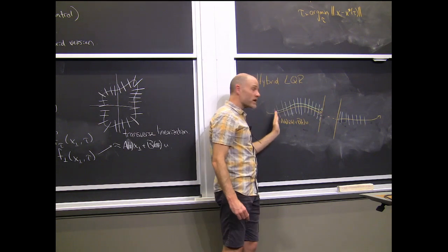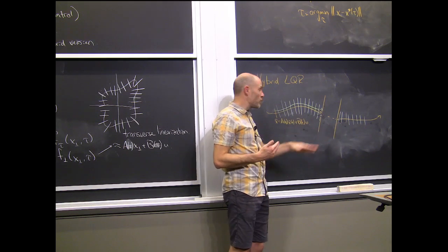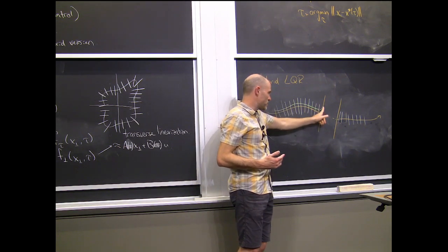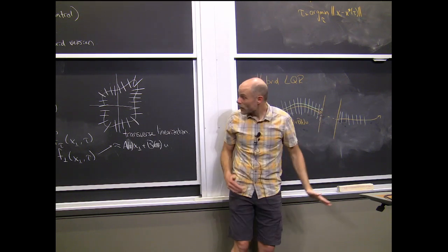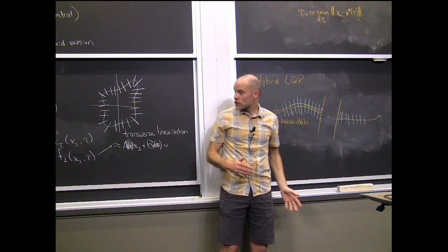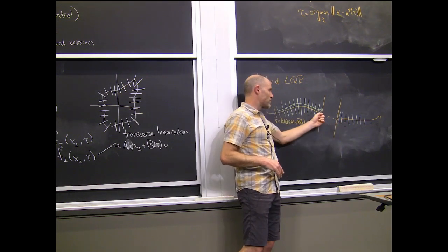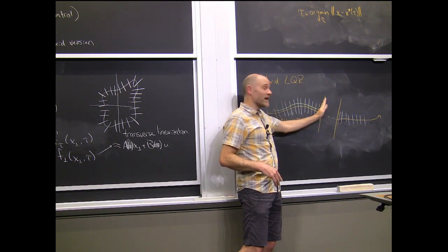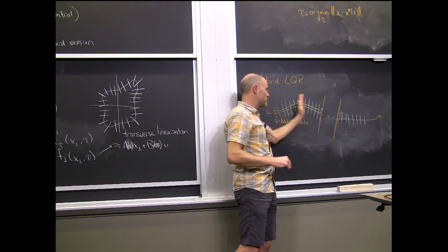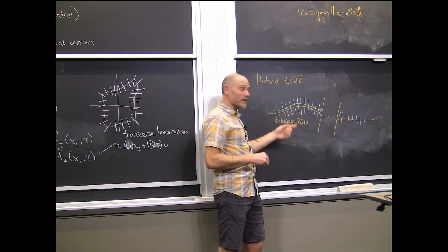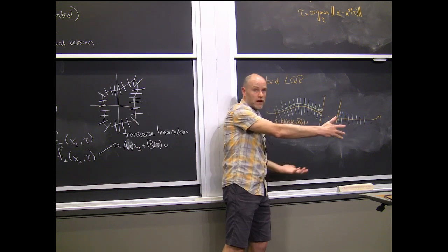So if we do it on the transverse coordinates, it's not absolute time on the nominal trajectory anymore. We now project back, potentially through this mapping, that's min over tau, wherever I wrote that, right? That extra power of doing min over tau gives you the ability to say, I'm on this side of the cycle and I have a gain ready to go, right? The K you get from full LQR must evolve at the original time in order to have guarantees on its performance.